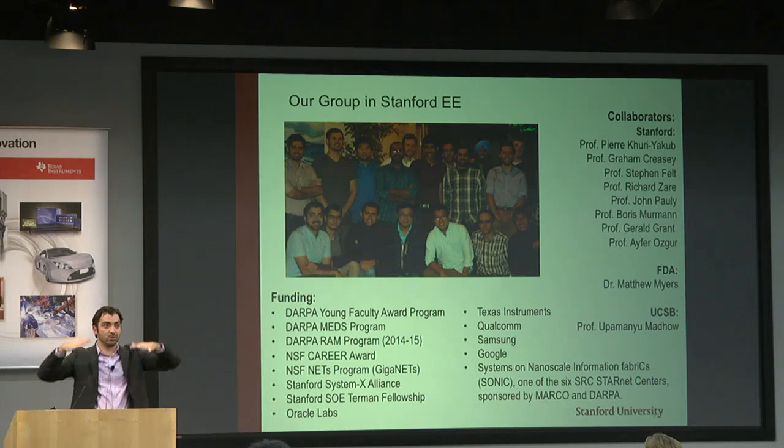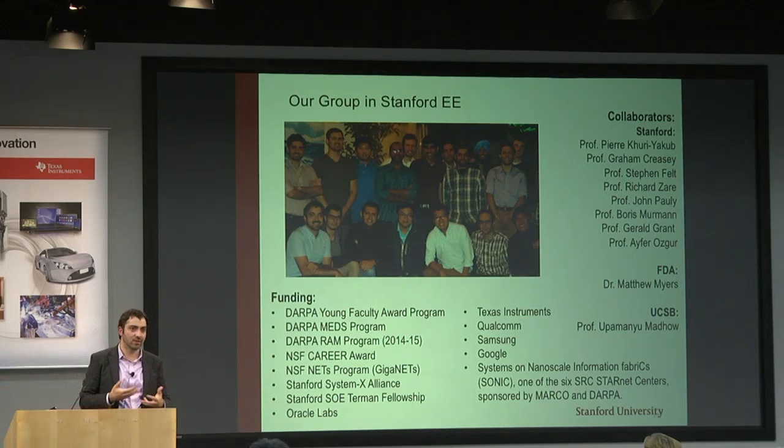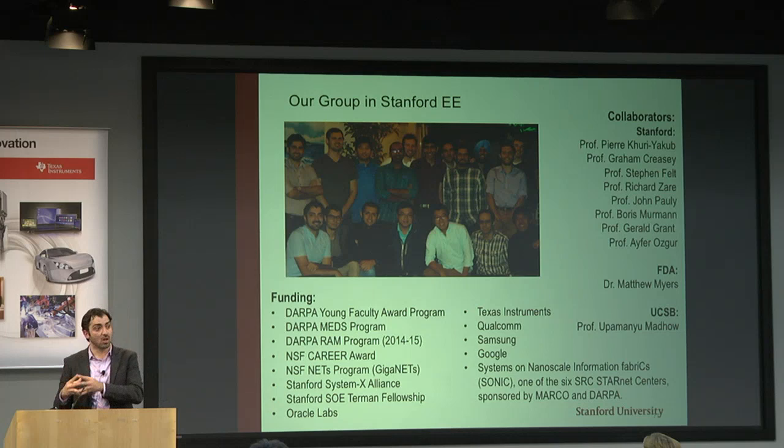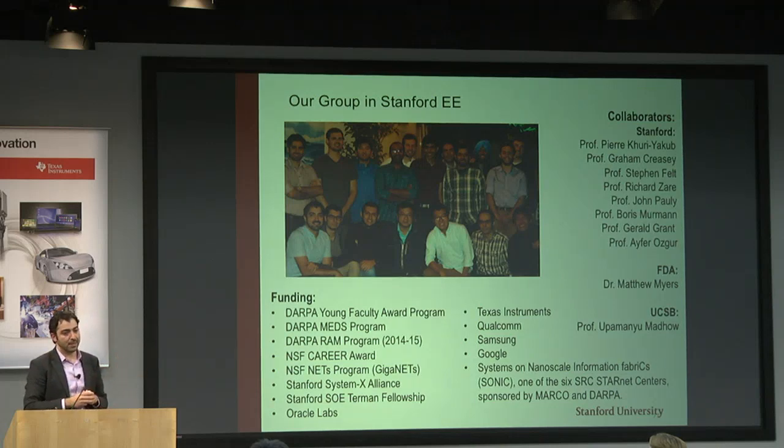In addition to frequency domain SAR and backpropagation, we've done some forward solving techniques. The idea of forward solving is, let's imagine the target was at point X, let's capture all the fields in a forward solution, and put it in the next position and the next position. So I have a solution for all the target locations, and I put it in a feedback loop and figure out where I am. That's computationally very exhaustive and not fast, but it's most accurate if it converges. On the question about iterative methods and whether it converges, we have some ideas. We published a paper maybe a year ago where we looked at specific filters that make the convergence a little more certain and make the forward solver a little more mainstream. But the trade-off between speed and accuracy always exists.